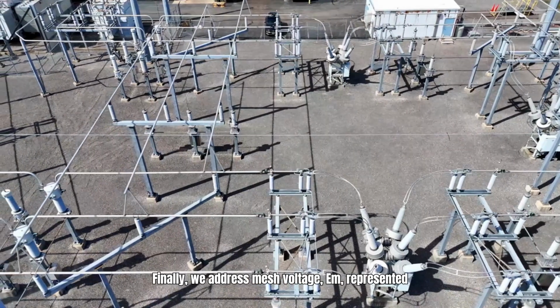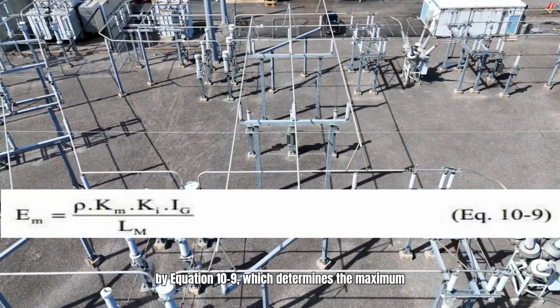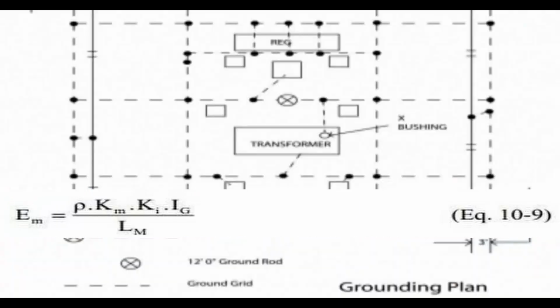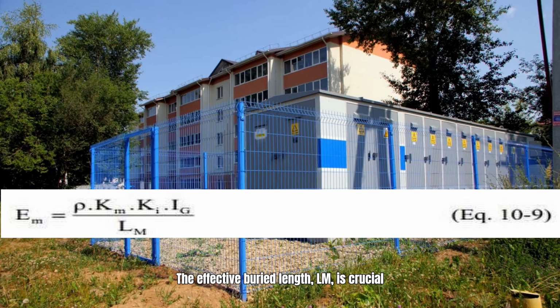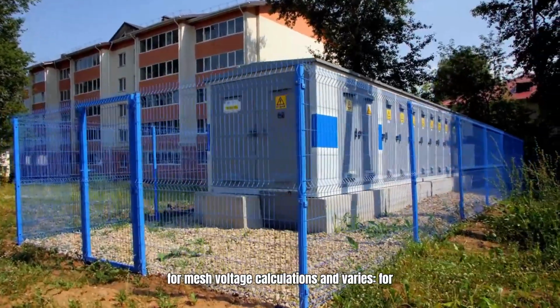Finally, we address mesh voltage, Em, represented by equation 10-9, which determines the maximum voltage difference within a single mesh of the grounding grid. This equation includes soil resistivity ρ, spacing factor Km for mesh voltage, and corrective factor Ki for grid geometry, where Ki equals 0.644 plus 0.148 n as per equation 10.10, along with Ig and effective length Lm. The effective buried length, Lm, is crucial for mesh voltage calculations and varies.